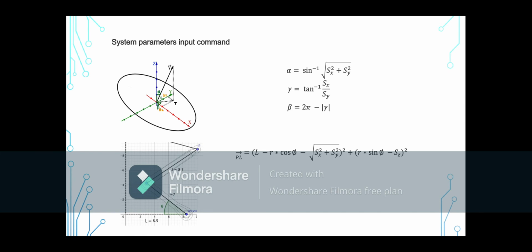So we can actually determine what angle theta the servo needs to move in order to generate the alpha, beta, and theta angles needed for the plate in order to bring the ball closer to the equilibrium point.